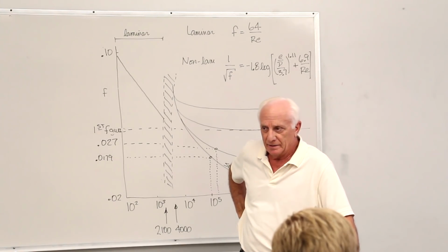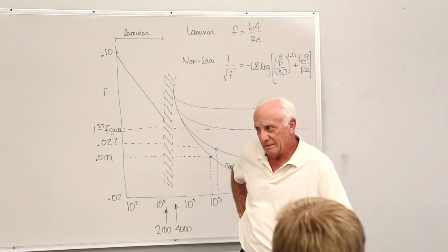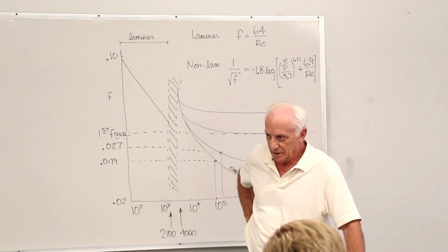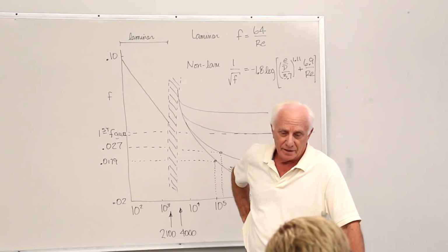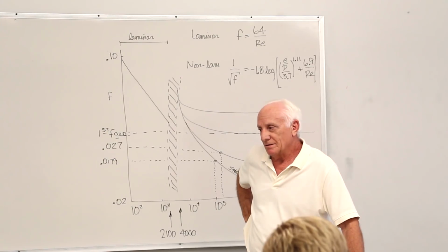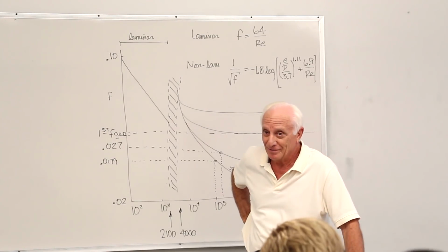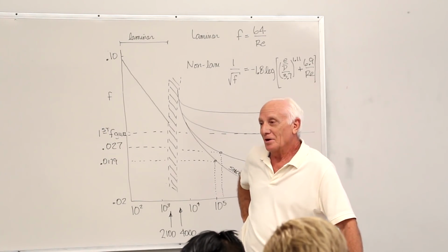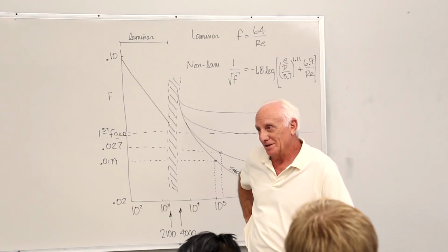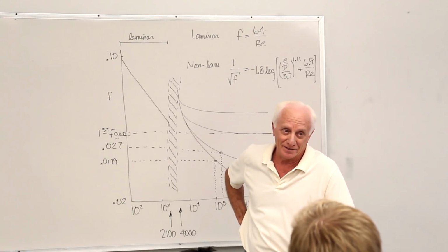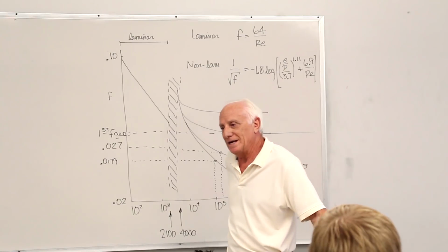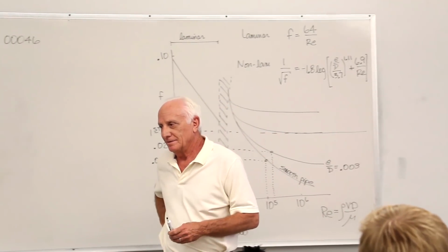Now, of course, if I go out and buy a 1-inch steel pipe, Schedule 40 by the way, is that 1 inch the inside diameter of the pipe? No. Is the 1 inch the outside diameter of the pipe? No. Conclusion: a 1-inch pipe doesn't have an ID of 1 inch and doesn't have an OD of 1 inch. That's why it's called a nominal pipe size.